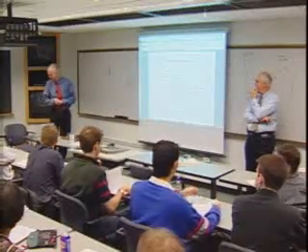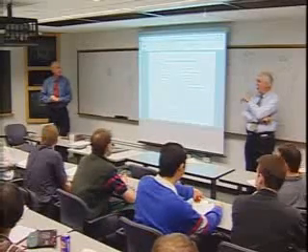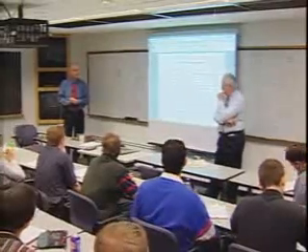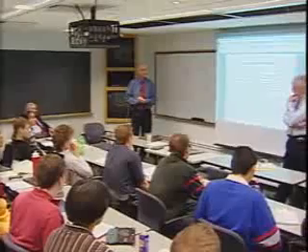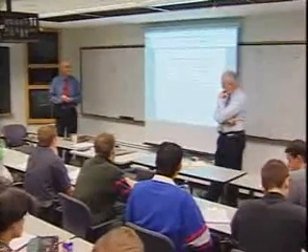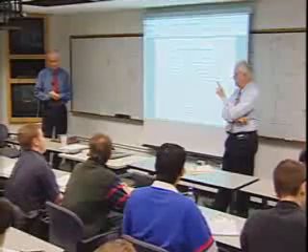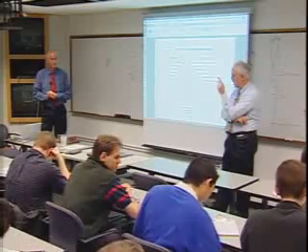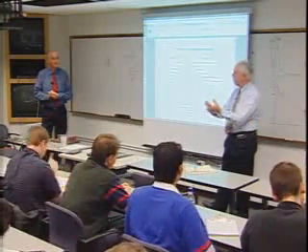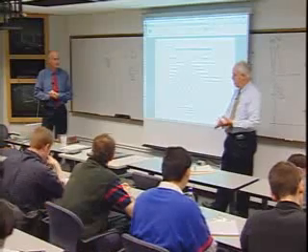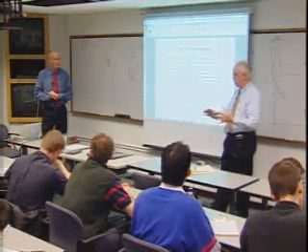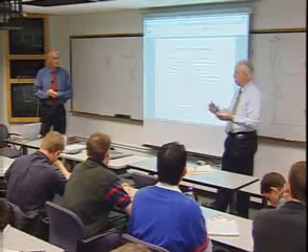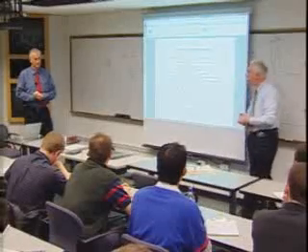If they want to do some simple calculations, what reference would you give? Is there any closed form simple calculations they could do? Fay and Riddell, probably. Detra, Kemp and Riddell is the approximate, and Fay and Riddell has the boundary layer activity. That's a crucial reference. In the paper that they have, the Shuttle Technology Conference, I have a list of references that were up to date in the various areas, whether it be surface catalysis, TPS, you name it. And those were the best references at the time. And the individuals named, many of them have gone on and done much better work, plus there are lots of younger people too. But I think that would be the best source.